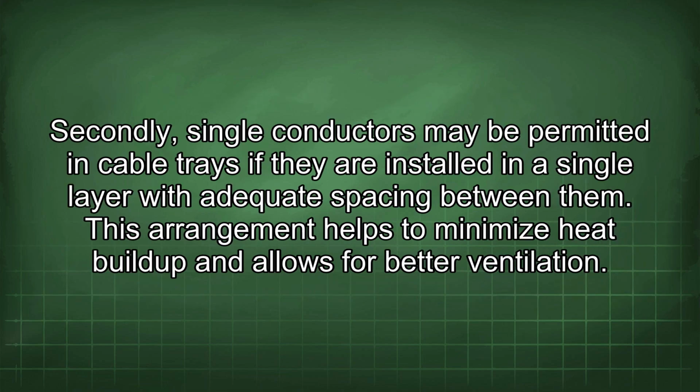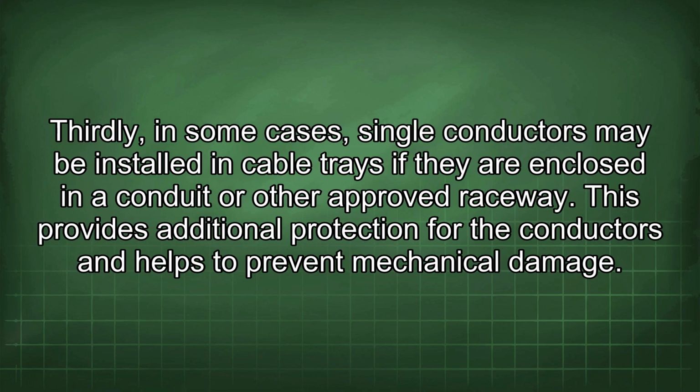Secondly, single conductors may be permitted in cable trays if they are installed in a single layer with adequate spacing between them. This arrangement helps to minimize heat buildup and allows for better ventilation. Thirdly, in some cases, single conductors may be installed in cable trays if they are enclosed in a conduit or other approved raceway. This provides additional protection for the conductors and helps to prevent mechanical damage.